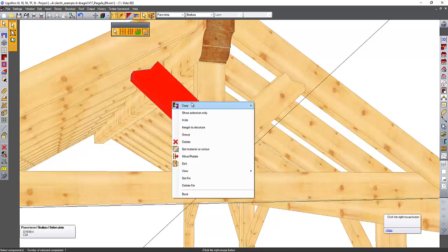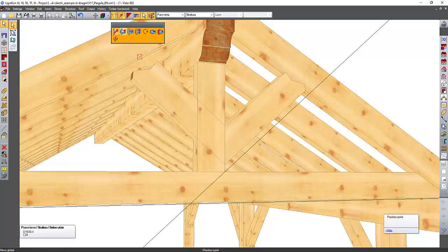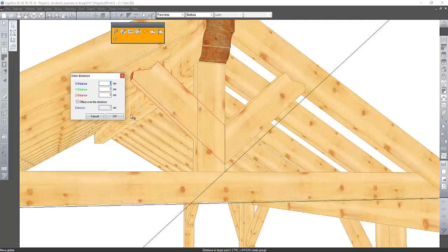We go here, we say move, we select move, we click the element, a moment, I click the right mouse button to do a step back. Now that I'm in the right position, I click. I can move with my mouse, but I have no guideline, so I stay in the same position. I click 2 times, and then when I see this, I directly move it in the X axis. I see this is 6.